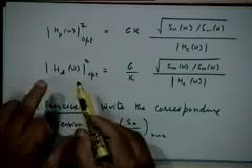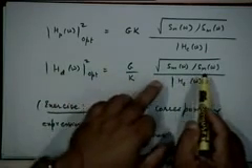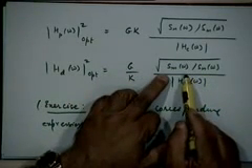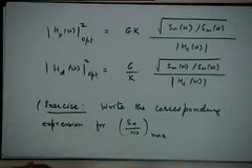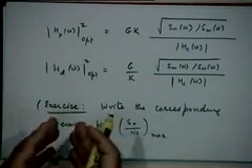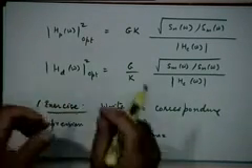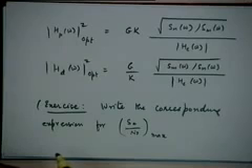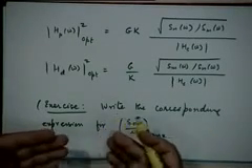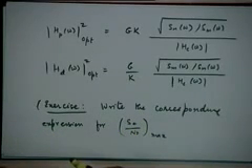Similarly, at the receiver, I must do the other way around, right? The de-emphasis filter is proportional to the ratio of the message power spectrum to the noise power spectrum, right? We want to suppress the noise spectrum, right? So wherever the signal to noise ratio is good, whichever portion of the spectrum, you put more weightage to that portion of the spectrum. Wherever the signal to noise ratio is poor, anyway you have lost some signal because of the poor SNR, you give less weightage to that portion of the spectrum, right? So you emphasize, rather de-emphasize the portion of the spectrum where the signal to noise ratio is poor, right?